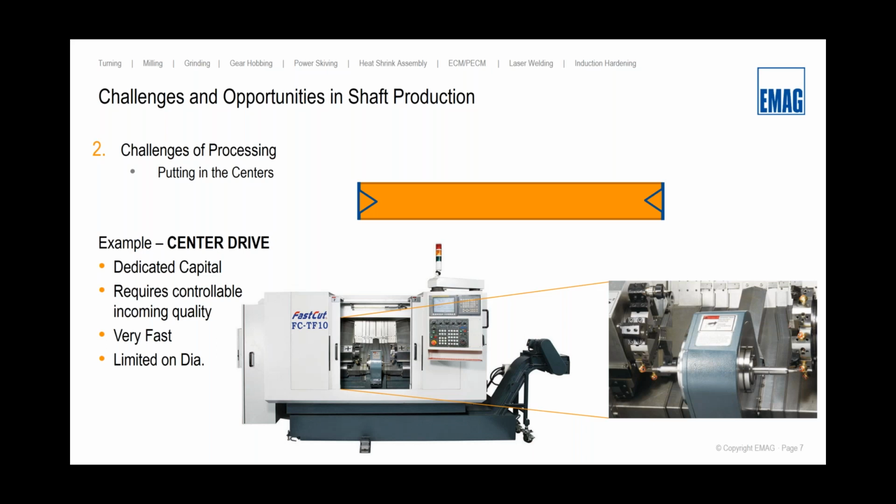It means your quality relationship from the features that you're turning on end A to those that you're turning on end B should be very good in relation to each other. And as I said previously, since centers largely are not used in the final application of the component in the assembly, it is really good to have good centers. You do have to have a relatively good incoming component.